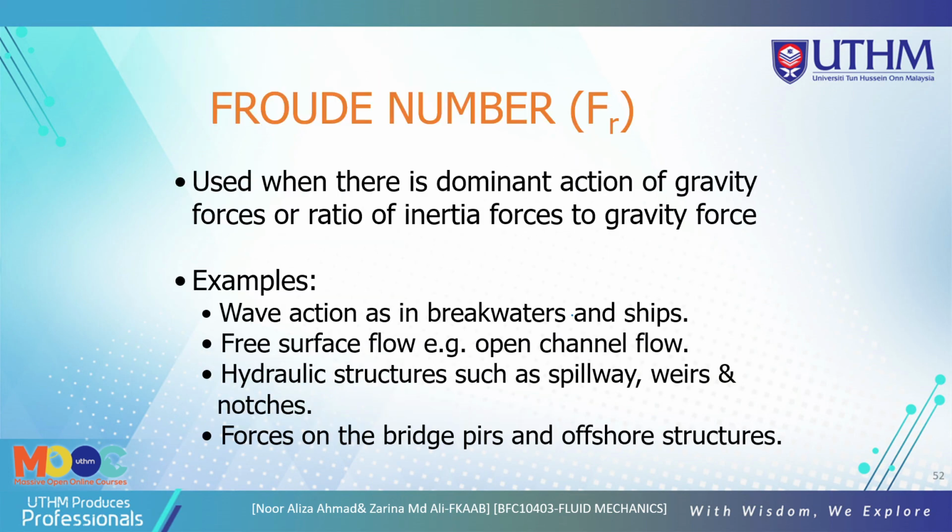And the Froude number is used when there is a dominant action of gravity forces, or the ratio of inertial force to gravity force. Examples with wave action, as in breakwaters, ships, free surface flow, hydraulic structures such as spillways, weirs, notches, forces on bridge piers, and offshore structures. So this is based on the Froude number.